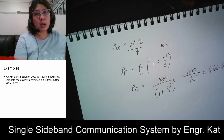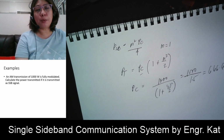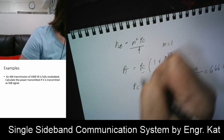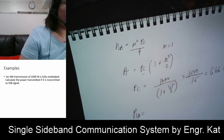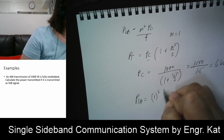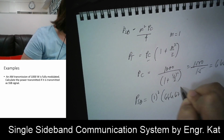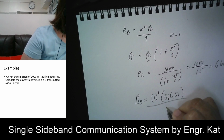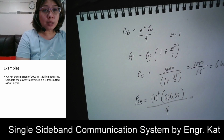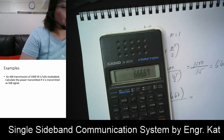Okay, so if we will be using this carrier, what will be the total transmitted power if we just make use of a single sideband AM? For a single sideband AM, this is equivalent to m squared, so that is 1 squared multiplied by 666.67 divided by 4. Okay, so that will give you 666.67 divided by 4.